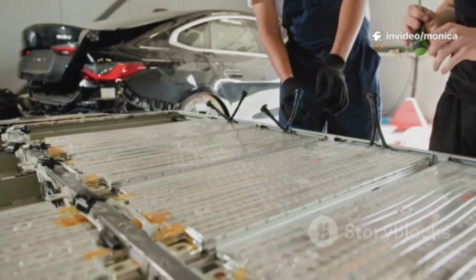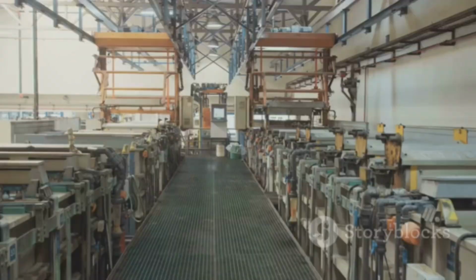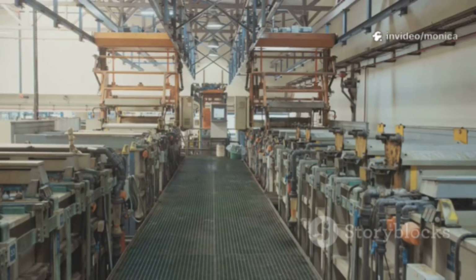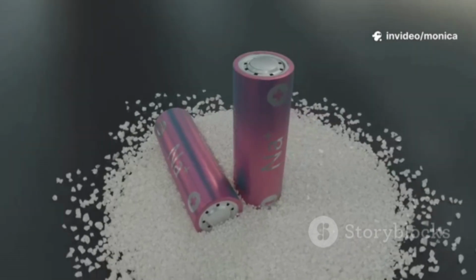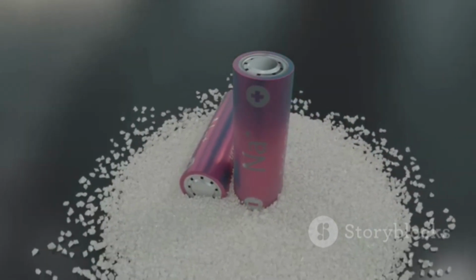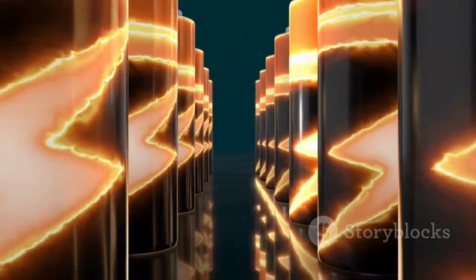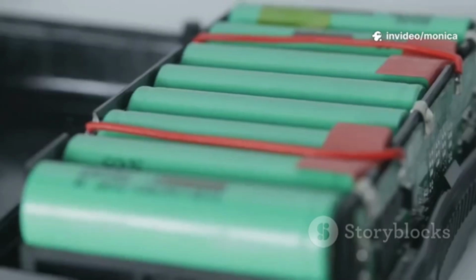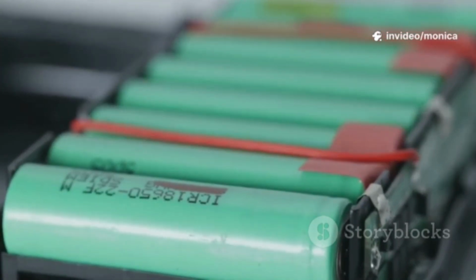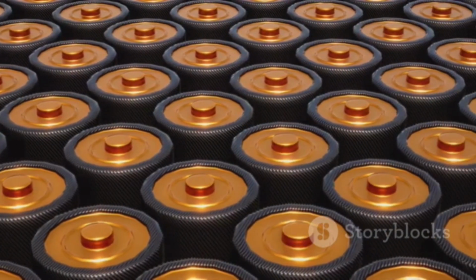For formation testing, as previously mentioned, this involves initial charging and cycling to establish performance metrics and identify any defective cells. End-of-line testing: final testing is conducted on the completed battery pack and includes performance testing, verifying capacity, internal resistance, and cycle life. And for safety testing, short circuit, overcharge, and thermal runaway tests are conducted to ensure safety standards are met.